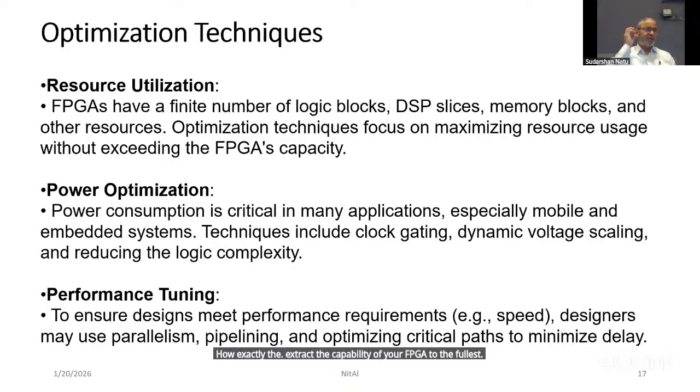And when you see a design as a case study, I'll show you what we could do there. Then power optimization, because power consumption is critical in any application, right? So when you are using these FPGA devices, you need to see what clocks they are getting, because the clock frequency will create more power dissipation, your dynamic voltage swing will be there, your IO operations will be there. So which particular blocks are operating, which blocks are not operating, all that needs to be taken into account. And overall performance tuning is really important, because you want to understand at what speed your design is running.